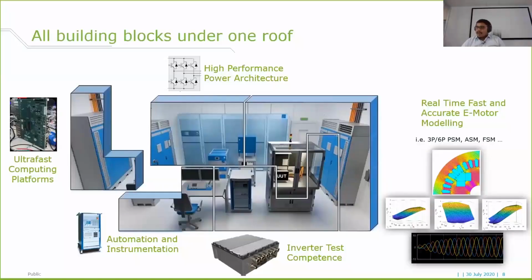We also provide automation and ultra-fast instrumentation. This is also one of the requirements for drive inverter testing, where the data acquisition rates are really high. We provide a voltage acquisition system at 25 megasamples per second with a tolerance of plus or minus 1%.